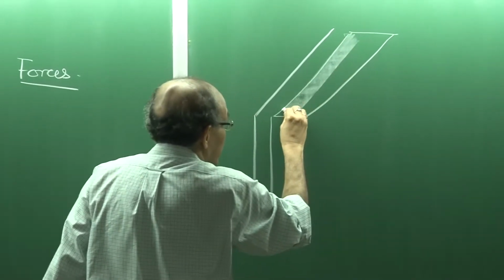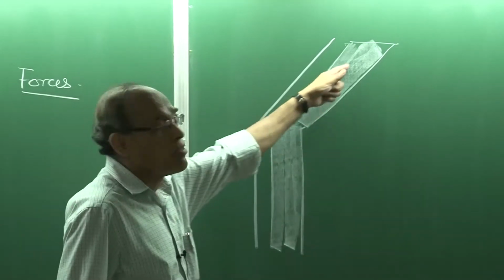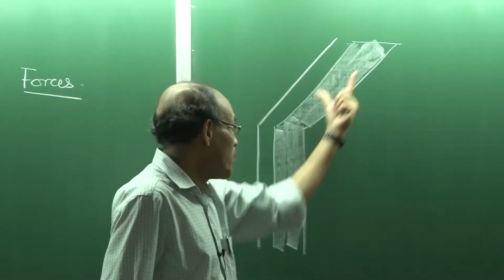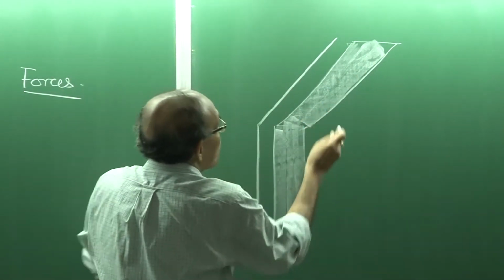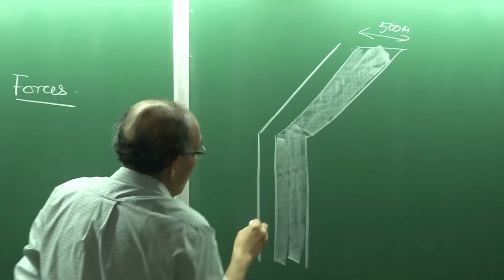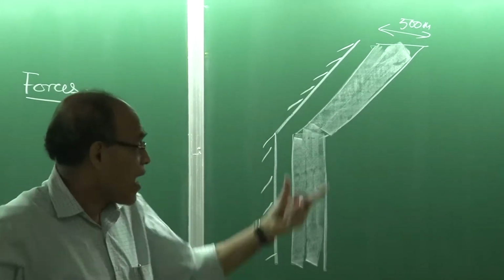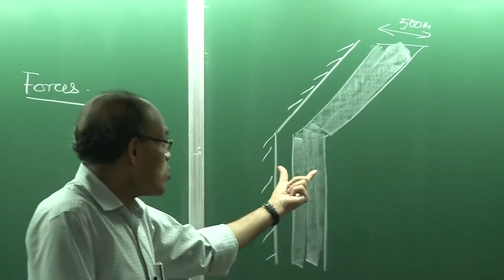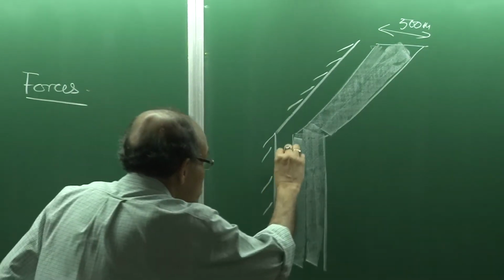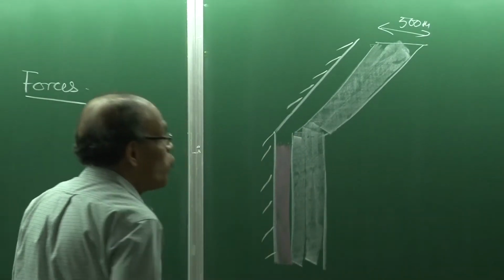So this is the slab we are talking about, and what could be the slab? The width we are talking about is about 1200 millimeter or 2000 millimeter. On the other hand, the thickness of the slab could be about 500 mm. It's a conventional slab, 500 mm or so. This is the outer boundary of the mold wall, and because the mold, being a high temperature operation, tends to expand, and because of solidification the ingot shrinks, a gap is created between the ingot and the mold. And it's through this gap that we have a flow of lubricant or fluid which is actually resting over the surface.